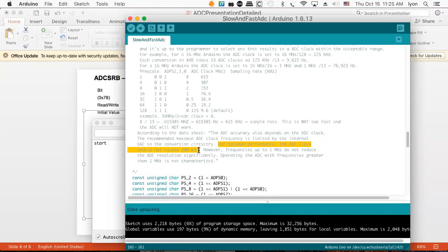That means I'm going to be down in the, I don't know, 9.6 kilohertz sample rate, because that's 125 kilohertz. Next one up is 250 kilohertz. So that doesn't really float my boat, because if I'm sampling at 9.6 kilohertz across two different ADC converters, I'm really down to a total sample rate for each converter of perhaps 4.8 kilohertz.